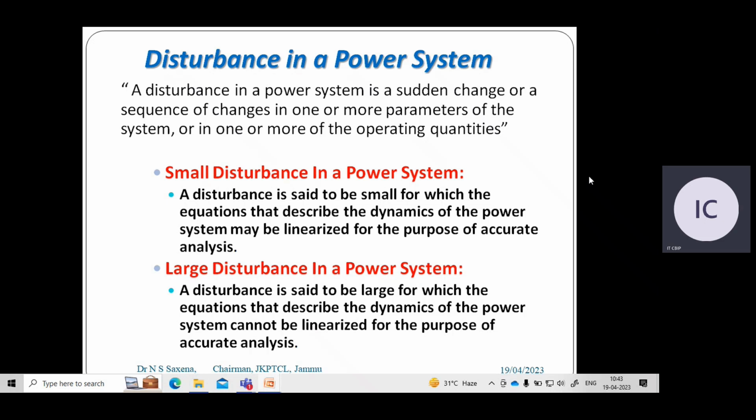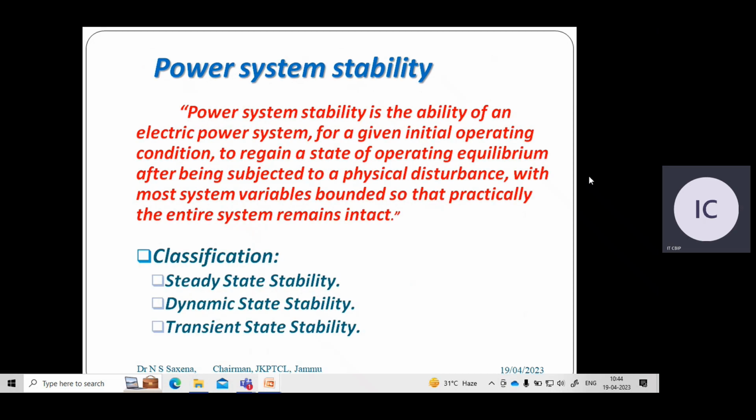Okay, right. How much time the fault persisted will also matter. That can also be judgmental, no, you can calculate. This is basically what you are saying is the critical clearing time. Yes sir, that is how much time the relay should take so that the system remains intact. Like in a generator, in a gas turbine, if the fault persists for more than 0.02 second and is not limited within it, then the system becomes unstable. Then this is critical. Critical means this side is stable and the other side is unstable. So that's the critical clearing time. We will see all these things today.